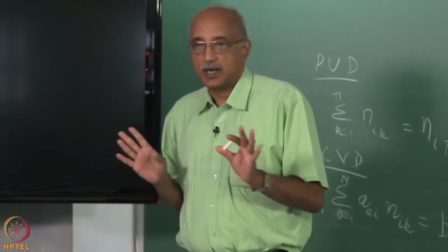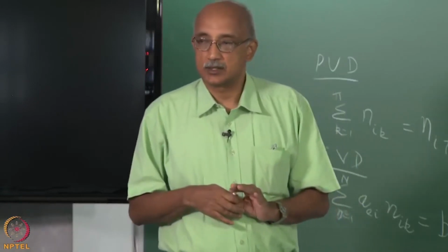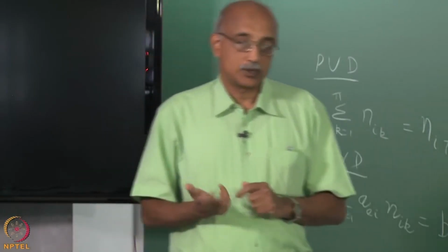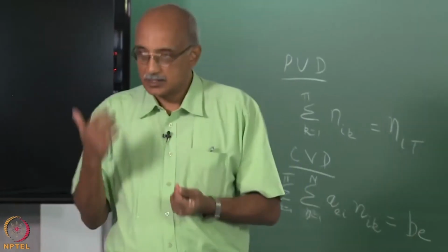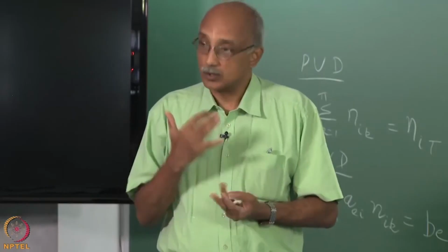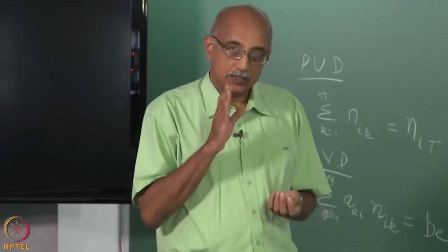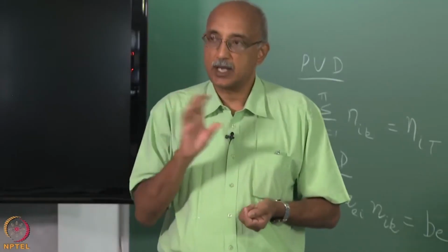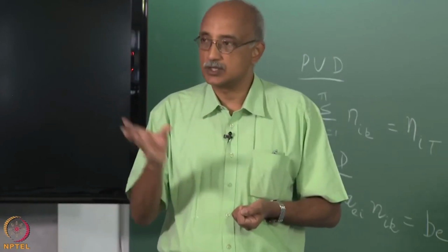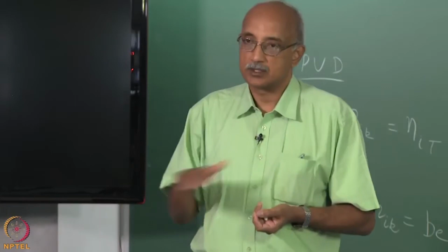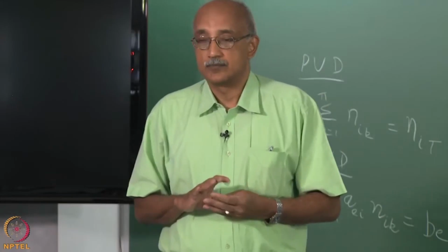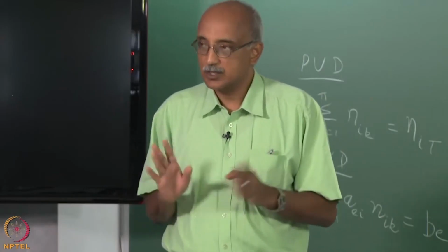So, now that we have a reasonably good handle on how to deal with the chemistry in CVD reactors, the second important aspect is the flow dynamics. The reason that flow dynamics are important is not only because they establish local pressures, local velocities and local temperatures, but also because they have a very direct influence on the transport of the reacting species into the reactor, and then the transport of the daughter species to the vicinity of the substrate on which you are trying to deposit the CVD film.